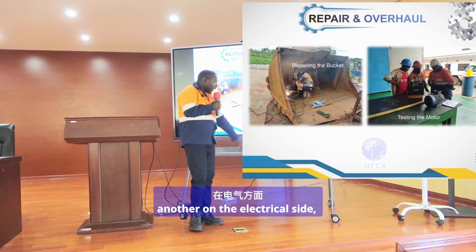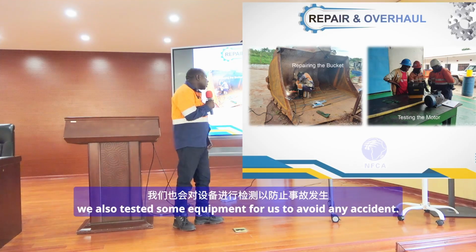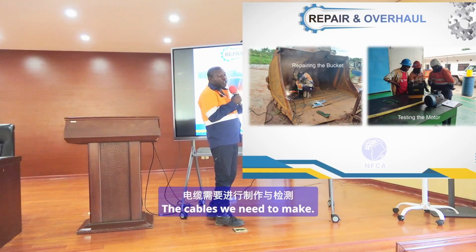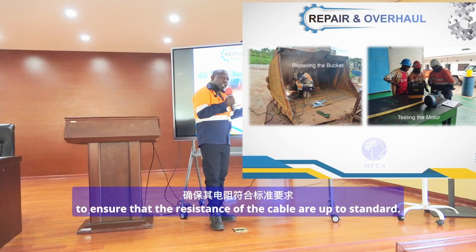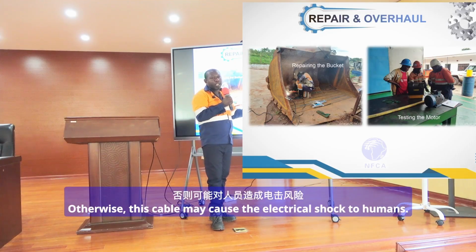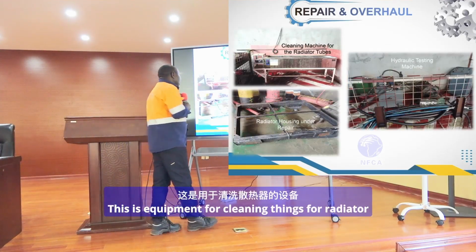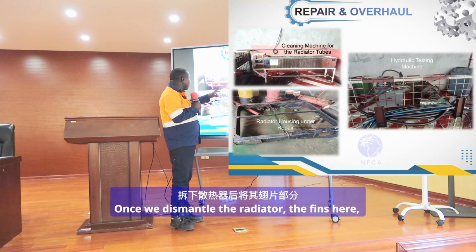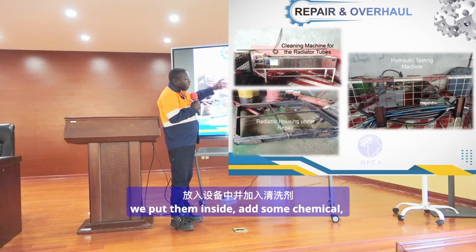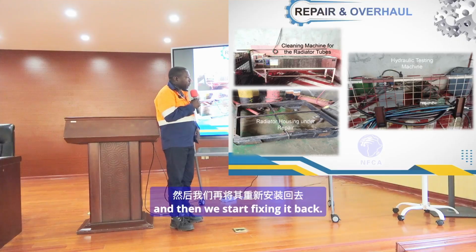Another, on the electrical side, we also test some equipment to avoid any accident. The cables we need to measure. We have periods when we need to measure the cables to ensure that the resistance of the cable is up to standard. Otherwise, this cable may cause electrical shock to humans. We have other equipment in the workshop. This is equipment for cleaning a radiator. Once we dismantle the radiator, the fins here, we put them inside, add some chemical, then let them boil for some time, and then we start fixing it back.